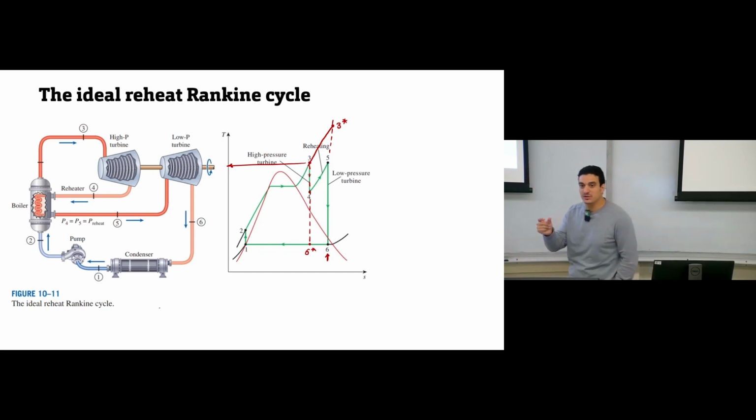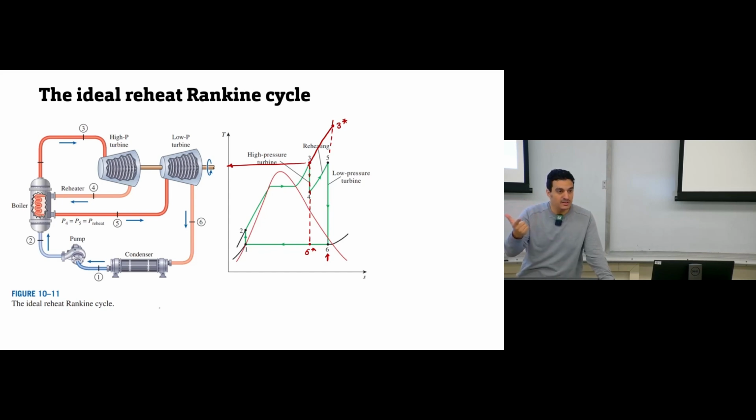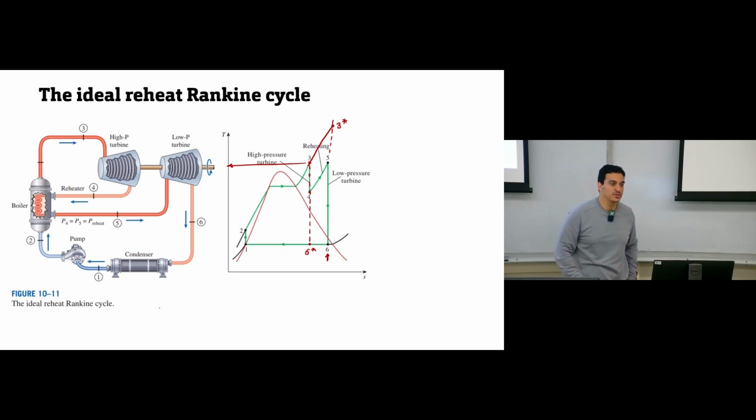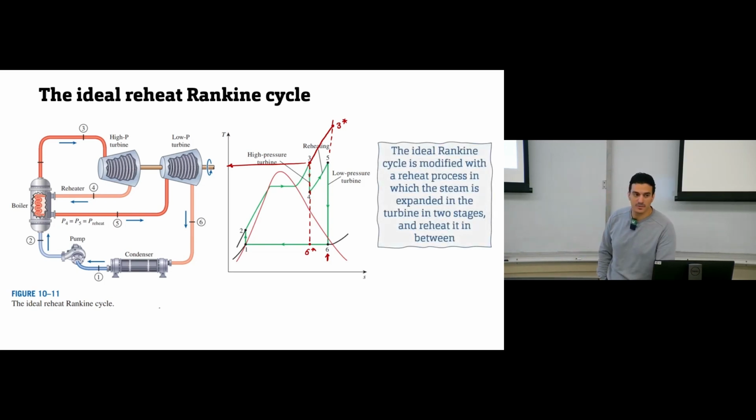So this reheat solves 2 problems that we can have in the Rankine cycle. It gives you more efficiency. It makes the phase of the outlet of the turbine very close to the single phase, very close to the vapor, without superheating the boiler outlet. So we don't need any special material of construction for this boiler, just with the simple idea that we have here. Clear?